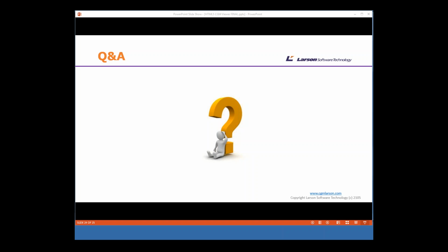So next question, does the JavaScript viewer zoom in and out by mouse wheel independently? Yes, I think I showed that in the demo, but it does zoom in and out with a mouse wheel, but you can, it was hooked up to the toolbar buttons to do it. We do it a couple of different ways, either with a drag a rectangle or click on a point to zoom up. Next question, does it handle composite CGM graphics including raster and vector? Yes, absolutely. Absolutely.